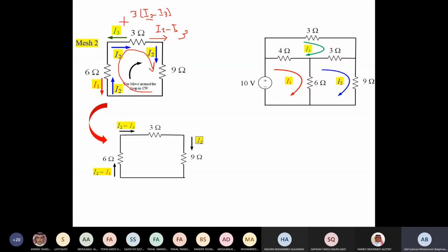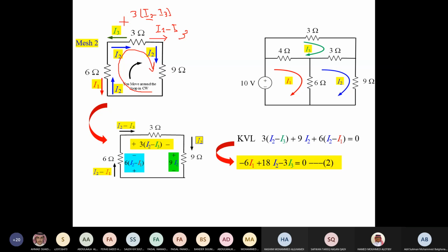Of course, what will happen, this is the current that is on the element because you are going in this direction. Okay, now the voltage is going to be this. The voltage drop on this element, the resistor. Okay, and I just write the KVL equation as shown over here. I simplify and I get this. Now I have 2 equations.